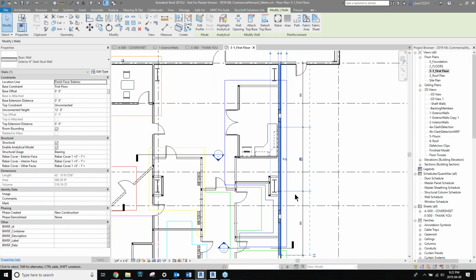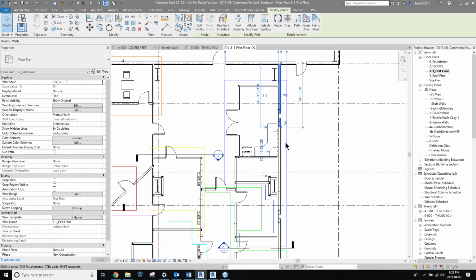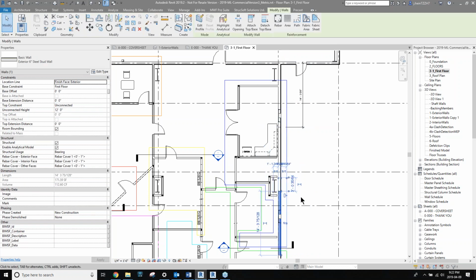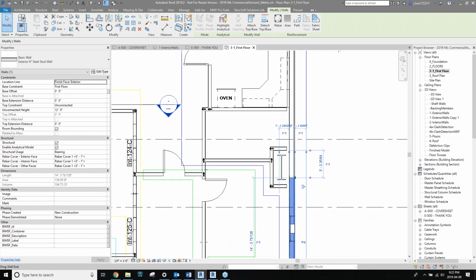This exterior wall is a total of 42 feet. I have some break marks that are just equal. Same thing, we go back up under markers and we have wall splitter. This happens really quick. I then just get 3 pieces of wall where my marker would have been. I could actually put a gap in here had I defined it in my marker.